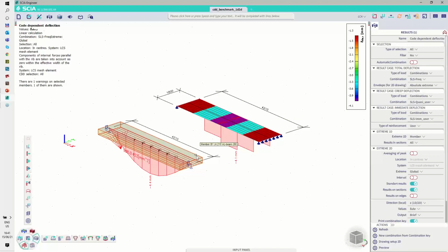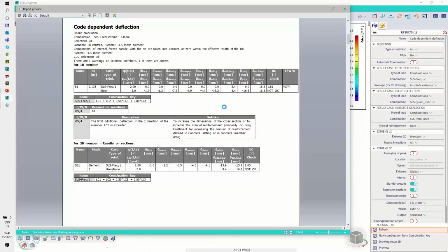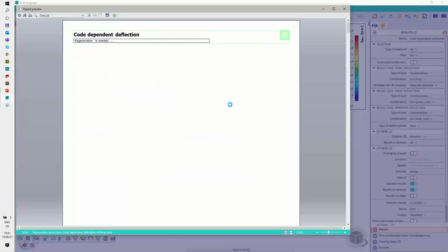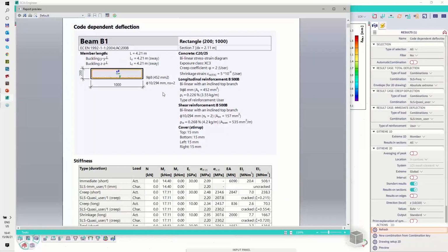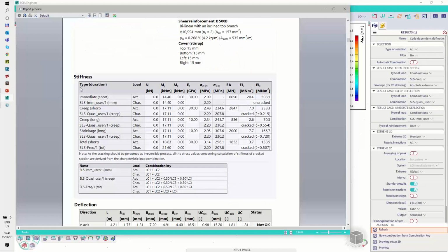If I go now to the detail output or standard output, doesn't matter. First, I will start with standard output. You will see the change. So now I do not have 4 load levels actually, but I have also another level for the shrinkage. Yeah. As I said, it's independent of the load, but to be able to calculate the stiffnesses, we actually need some load level.